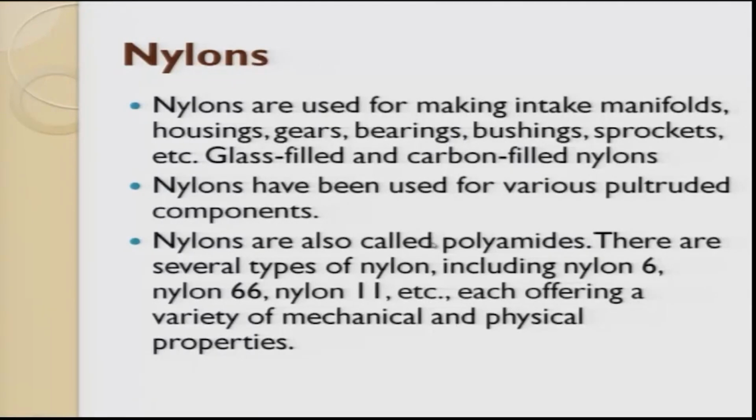Nylons are exhaustively used in the intake manifold. They are used as gears. In printers we use nylon gears, wherein it has low friction. It is used as bearing material, bushings, sprockets, etc.